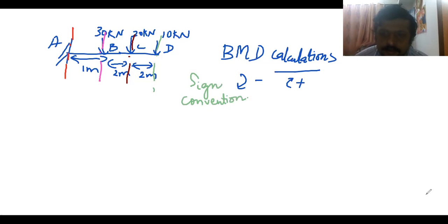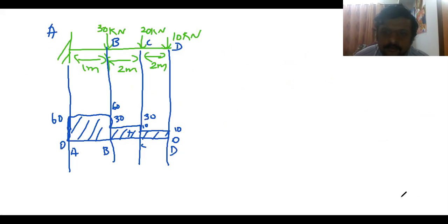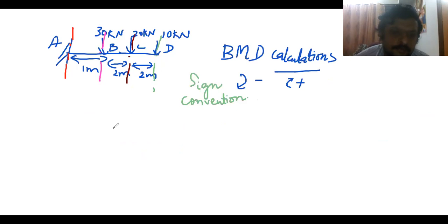I have used, and here for shear force it was, this is the sign convention. So very simple, students. So what we'll do, BM, bending moment at D. At D there is only load acting, but is there any force? Bending moment is force into distance. Force is acting, there's no load. So we'll say 10 into 0. So it is 0 kilonewton meter.